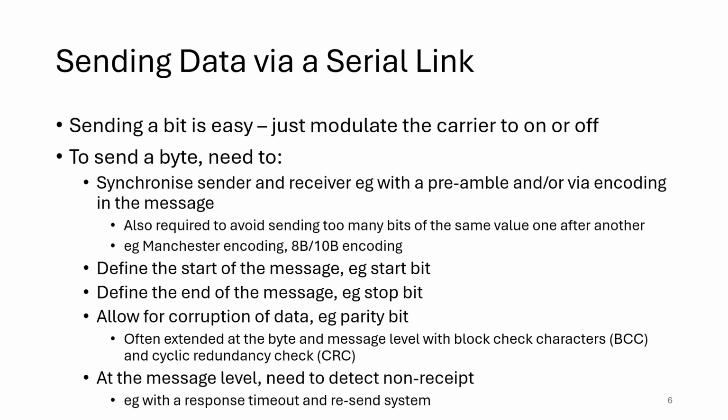At the message level, we also need to detect non-receipt. Some systems use broadcast messages, but in most applications, we need to send the message and we need to detect if the message was received. So typically that's with some sort of response timeout. And if the message wasn't received, we need to resend.